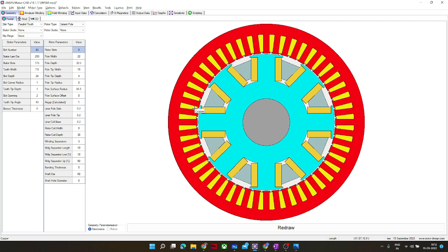Tesla used induction motors earlier, but now they shifted to IPM, interior permanent magnet synchronous motors. I read about it in an article. Yes, it is very interesting if you track all those things. The last day I was discussing, they can produce reluctance torque as well as electromagnetic torque, so they achieve both advantages.